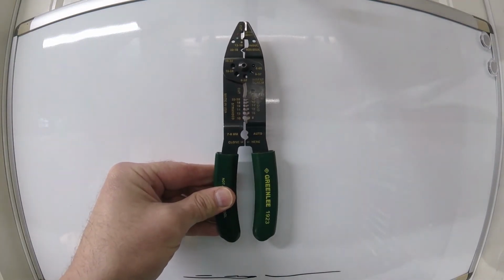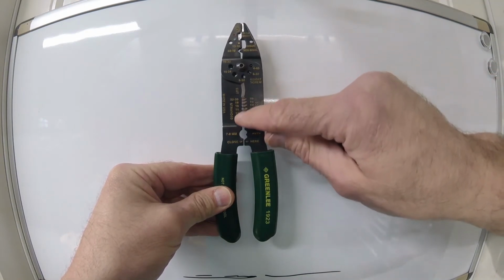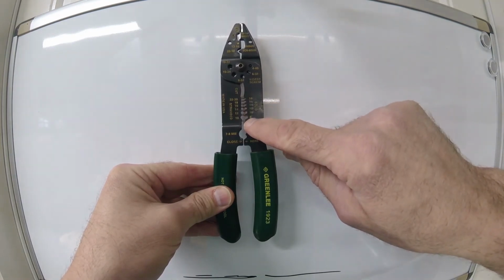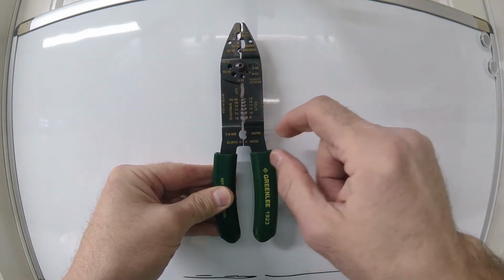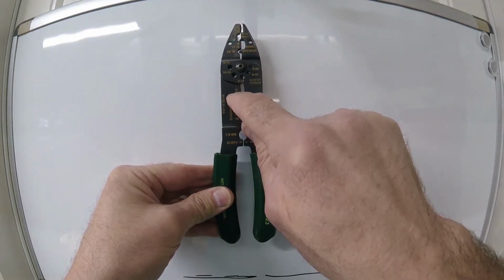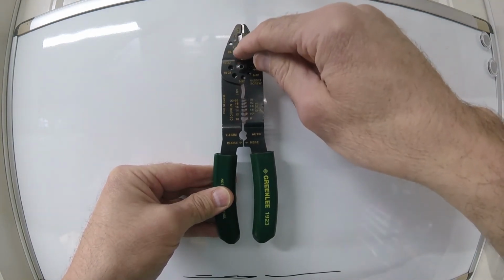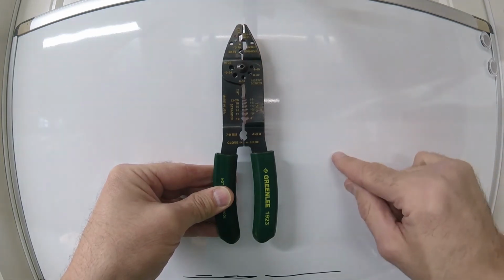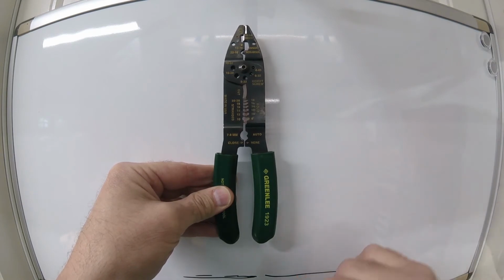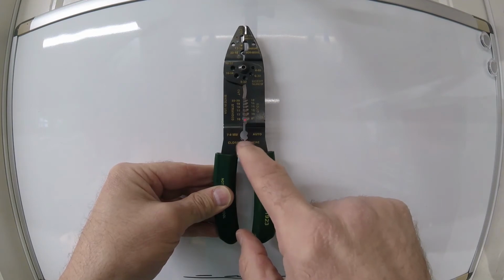And this is a combination of wire stripper. That's this section right here with these different size holes, and you see numbers next to them that correspond to different size wires. And this also has several different places where you can cut wire. Here's one section here for wire cutting, and there's another section up here. And then these 3 areas here are for crimping connectors onto wires, and I'll show you how to do that in another lesson. And this is another crimper. This is a little more specialized. I think that's for ignition wires.